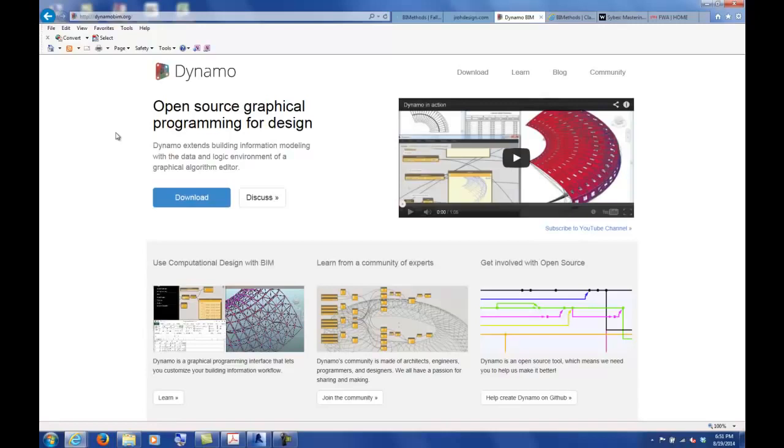Essentially everything that you could do in Grasshopper for Rhinoceros, you can do with Dynamo and even more, because Revit has a lot more built-in capabilities that are parametric and data-driven, whereas in Rhino, Grasshopper made all the parameters for you, and you had to do a lot of programming in order to make anything parametric. There are a lot of inherent capabilities in Revit that already have that built in, so Dynamo just enhances those capabilities and allows you to do a lot more components.